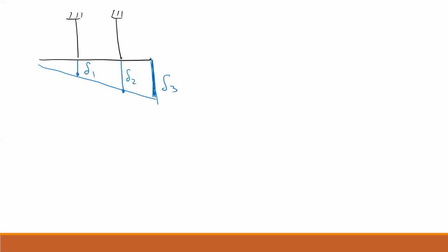You know that if this is a rigid platform, that whole thing is going to rotate. So you can look at, say, this triangle, and we can look at that triangle, and because they share an angle, we know that they're going to be similar triangles. So this leg here is going to be del 2 minus del 1, and this leg over here is del 3 minus del 1.